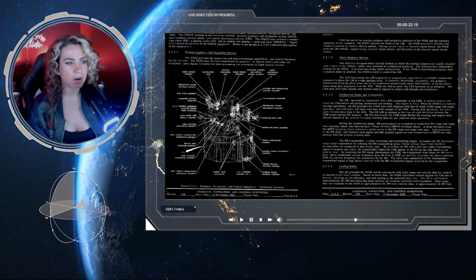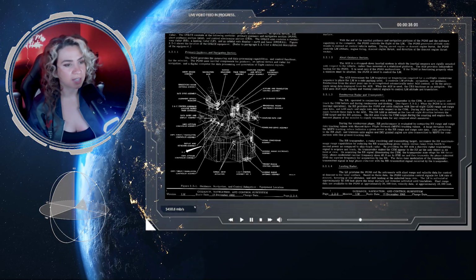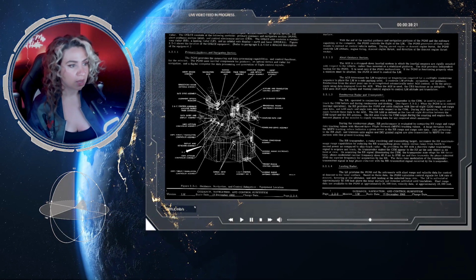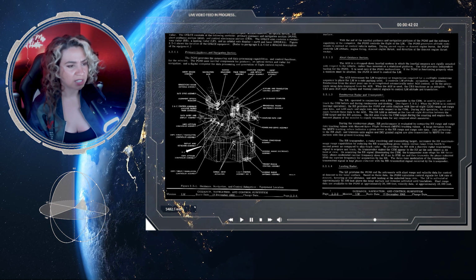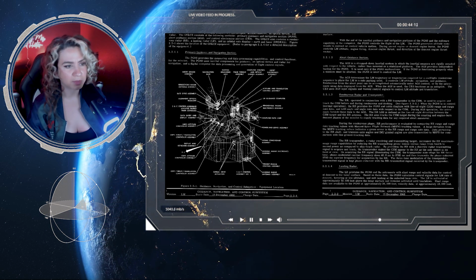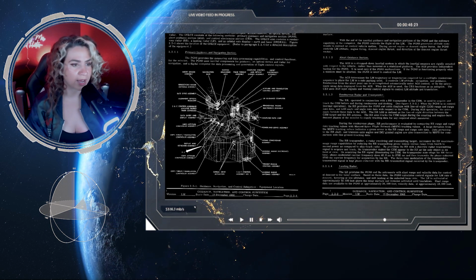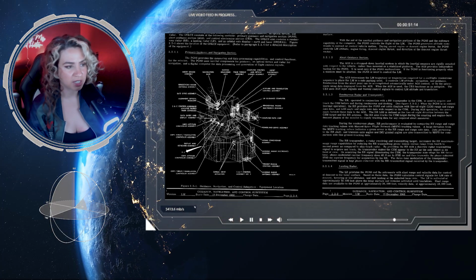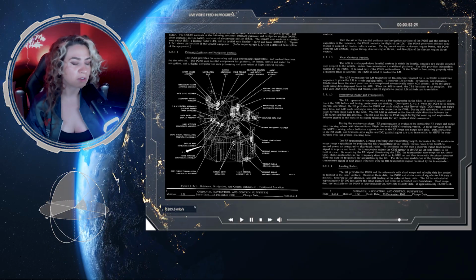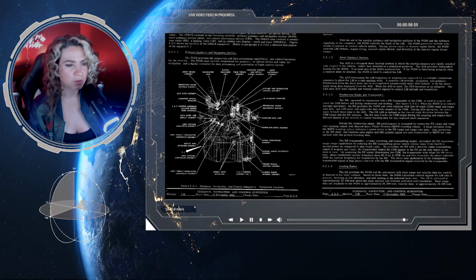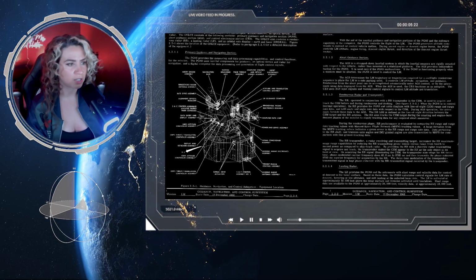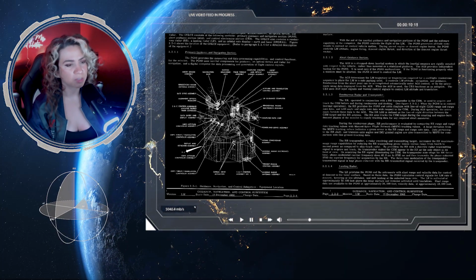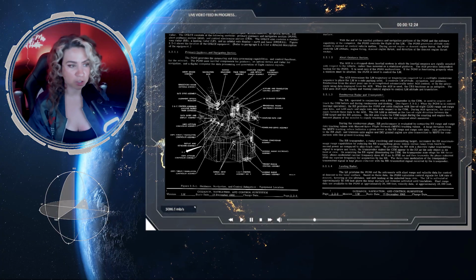On acquiring the RR signal illuminating the CSM, the transponder sidesteps the RR 3-tone phase modulated carrier frequency down to 40.8 MC to 9792 MC, and then transmits the phase coherent 9792-MC carrier frequency for the acquisition by the RR. The 3-tone modulation of the transponder transmitted signal is kept phase coherent with the RR transmitted signal received by the transponder.